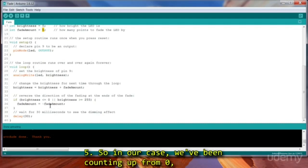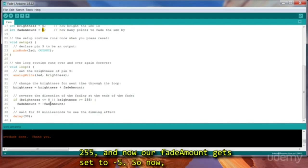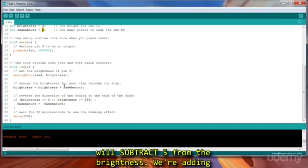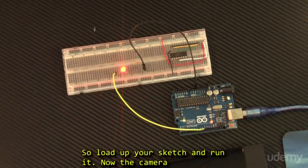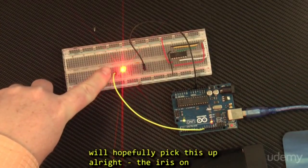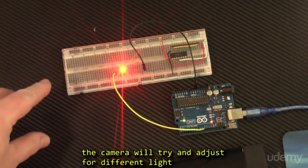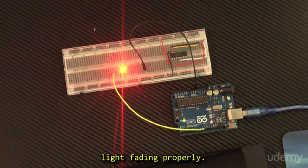So in our case, we've been counting up from 0, adding 5 every time we went through the loop. We hit 255, and now our fadeAmount gets set to -5. So now every time it loops through the loop function, it will subtract 5 from the brightness. We're adding a -5, right? So load up your sketch and run it. Now the camera will hopefully pick this up all right. The iris on the camera will try to adjust for different light intensities. So hopefully you'll actually see the light fading properly.